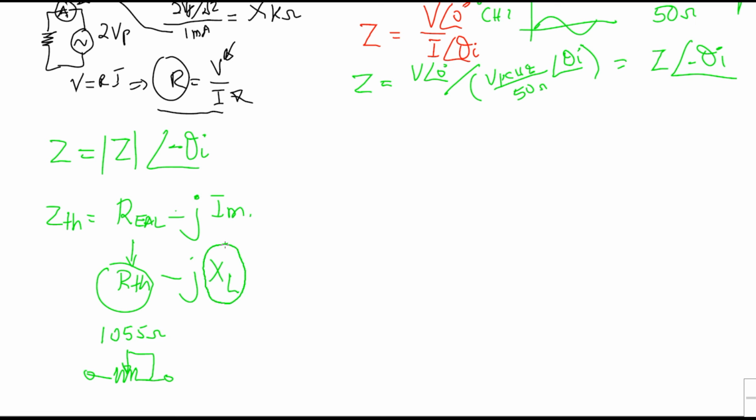The value coming from your calculation, XL divided by 2 pi f, will give us our L to be used in our circuit. Since we have only one inductor in our circuit, it comes back to the same inductor we used before in our original circuit, 10 millihenry. So this is our Z Thevenin.